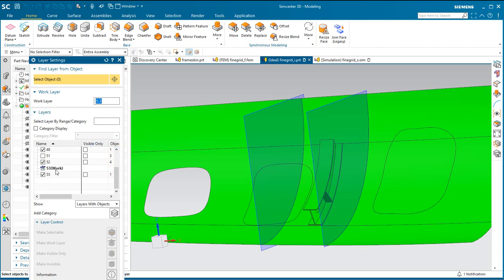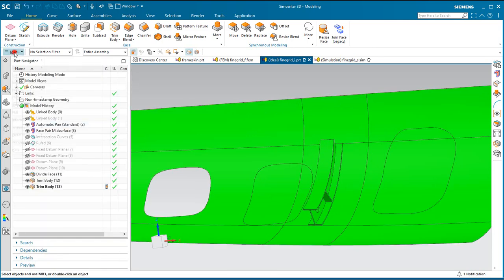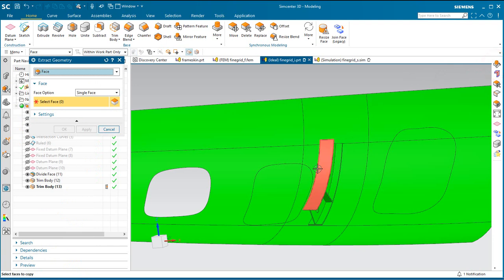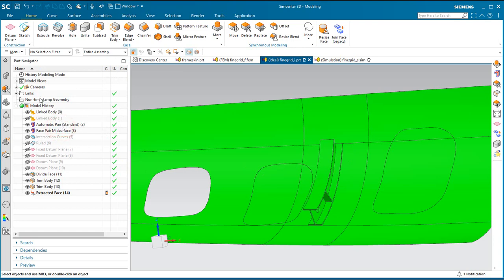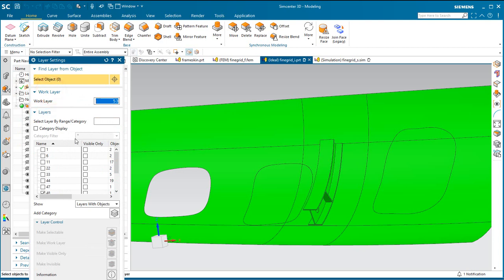And next we could mid-surface the frame, but we don't want the bottom or the OD flange of that frame to not be coincident with the skin. We actually want it to be exactly coincident with the skin mid-surface. That will facilitate creating a zero length C-bush in just a moment.